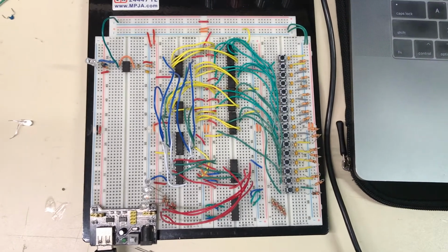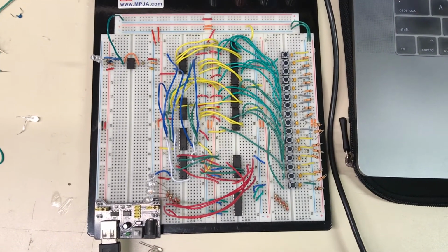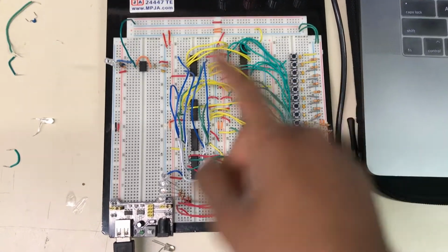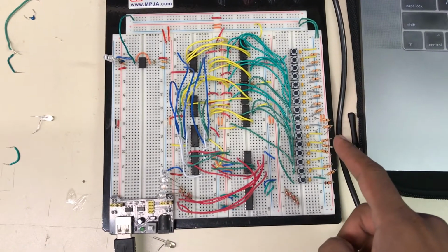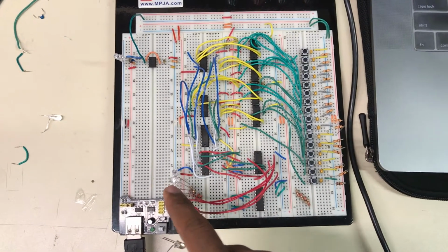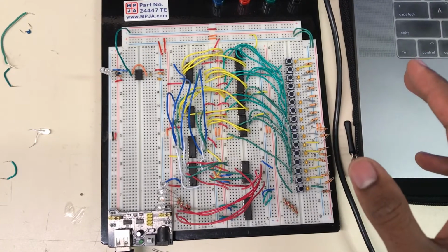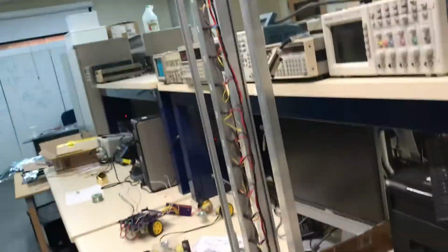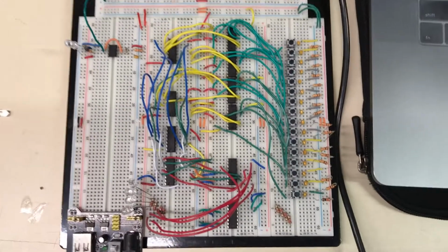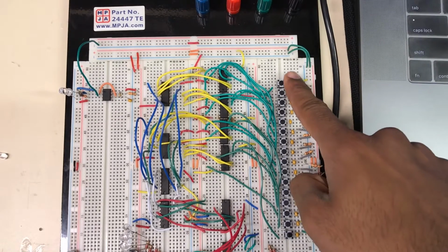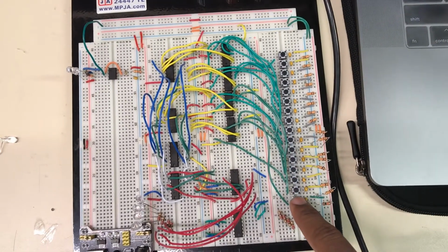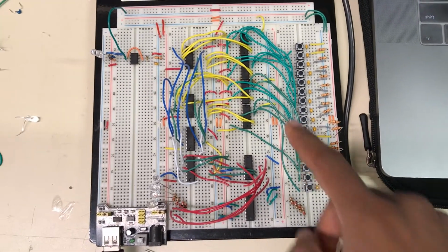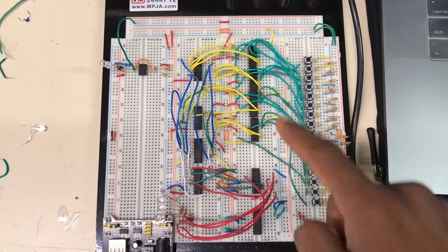Alright, so this is a preliminary demonstration of the encoding part of the elevator. So what I'm going to demonstrate in this video is that this circuit here can encode the input from the buttons into 4-bit binary. So I'll start by talking through how this circuit works. The inputs are these 16 buttons here, each one representing a different floor on the elevator. So what's happening is the inputs from each of these buttons are high unless you press the button, in which case they turn low. And so these data are then stored in these 4 registers here.